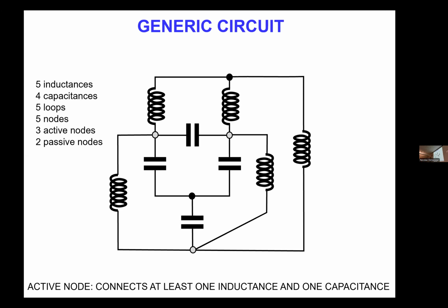Is it possible for the capacitance to be convertible? It looks like you would without the capacitance. Yes. Well, you can always invert capacitance matrices if you add always some little parasitic capacitances. There's always some residual capacitance between any node and the ground. So I don't think that's really a problem in general.